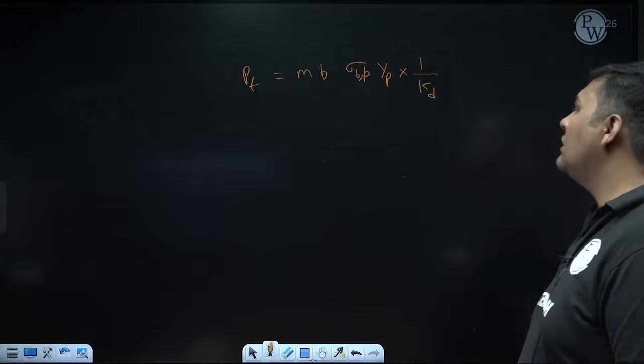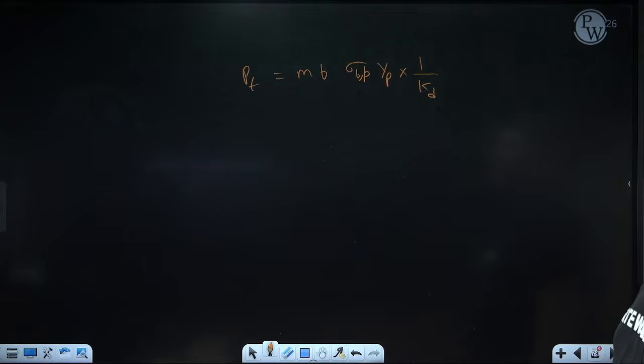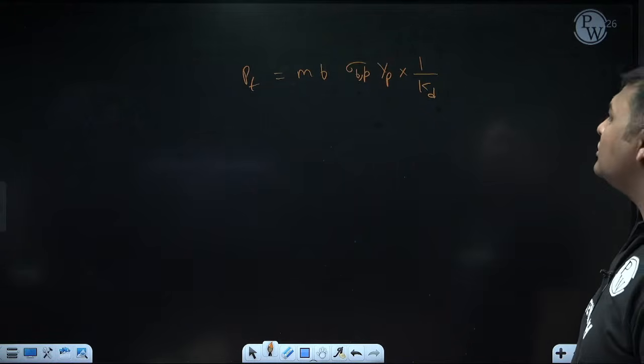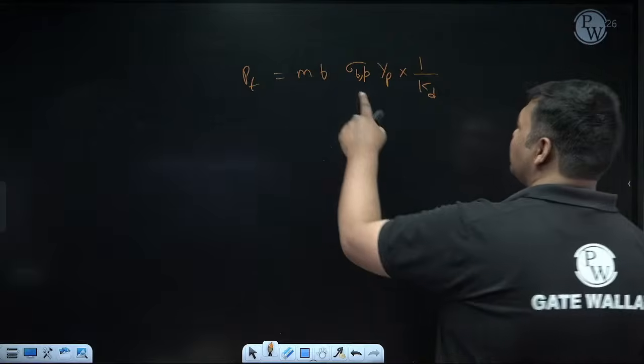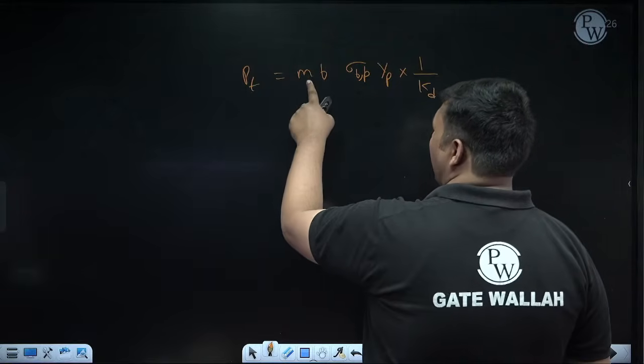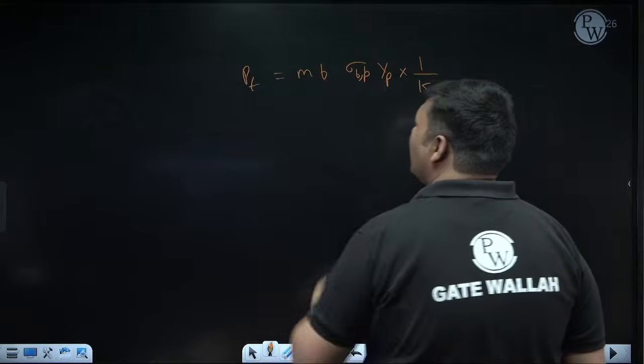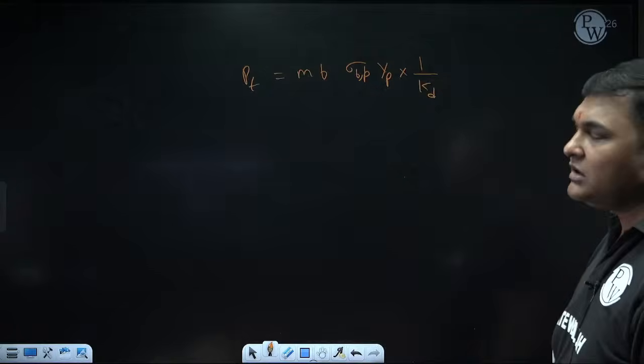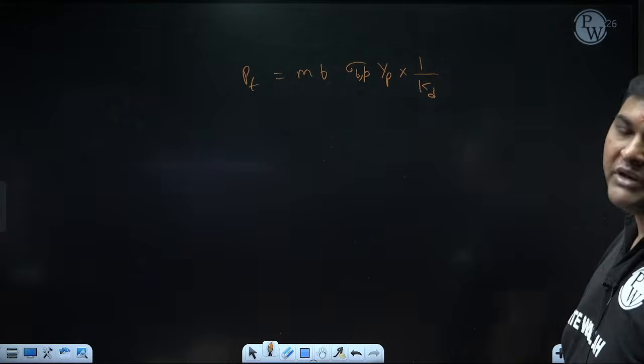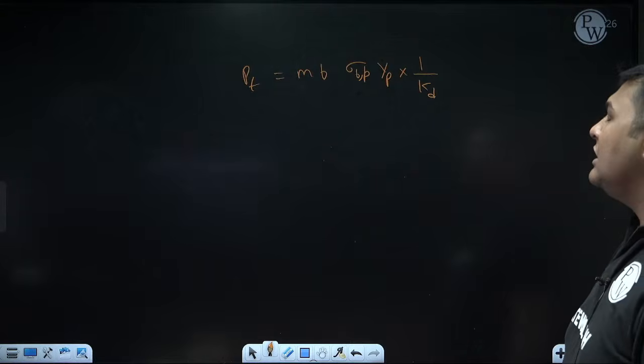And why is pinion weaker? Because permissible stresses of both gears are the same. Now through this we can find the limiting value of face width, that is b. KD is given, m is given. Now to calculate b, first I need to find the value of PT, which is the tangential force. Don't say we have to calculate tangential force of pinion. It will come the same for both pinion and wheel.